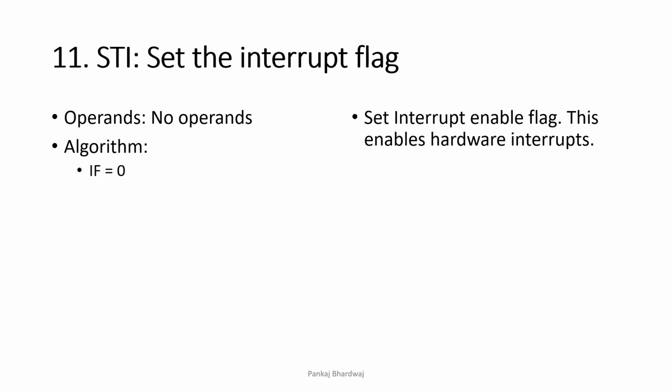Next is STI, set interrupt flag. That means IF is 1. When IF is 1, the interrupt flag is set. That means it enables the hardware interrupt. Now the hardware interrupts can be read from the hardware interrupt pins, that is NMI as well as INTR.